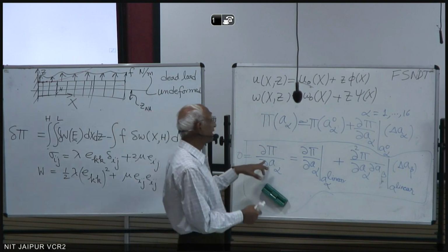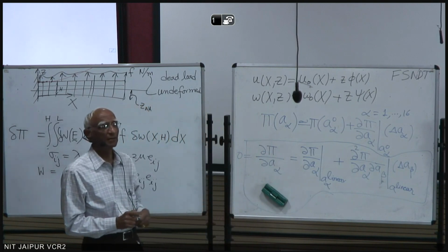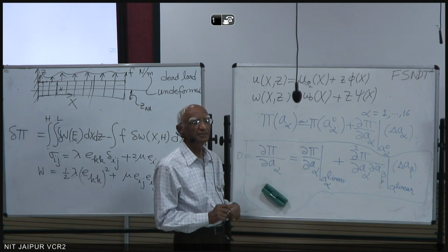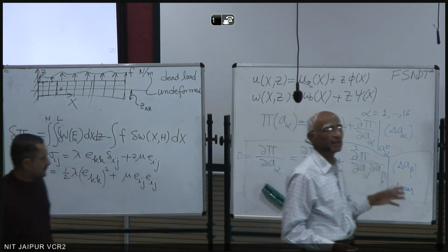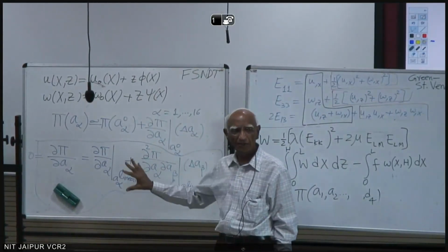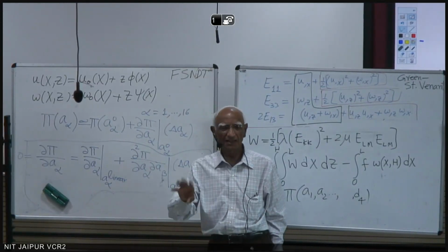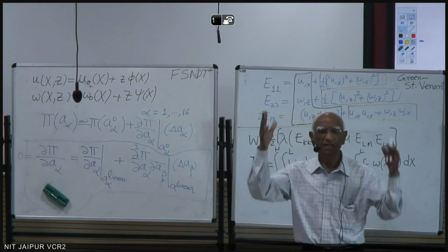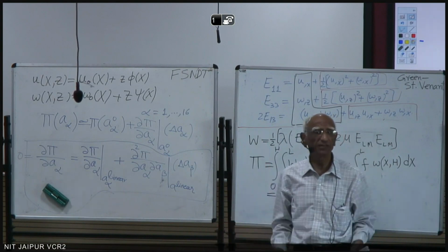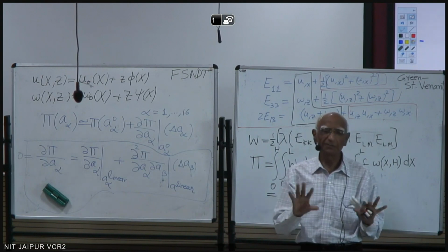No, because I'm differentiating already once. I could have given this thing a different name. So what will happen is that you need to solve K delta A equal to F every time you update K, like we did yesterday, every time we updated our thermal conductivity. So here we are updating our stiffness matrix every time. And it will converge depending upon the initial guesses.